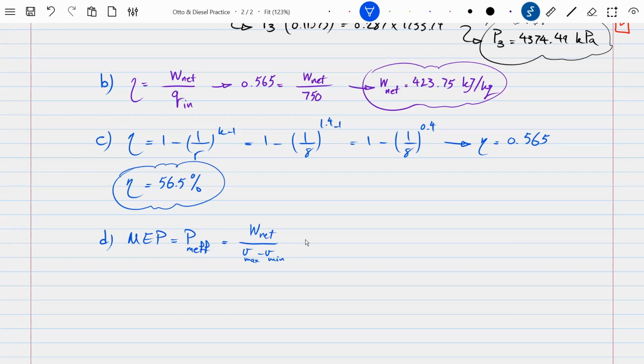It's a pseudo pressure that helps us engineers to gauge the output of an engine without knowing all the details of the compression ratio, the highest temperature, the lowest temperature. Without knowing all of that, this pseudo pressure, MEP or PMEFF, just gives us what we want to know. As long as you know the mean effective pressure and the displaced volume of your engine, you know how much power you can get out of this engine.